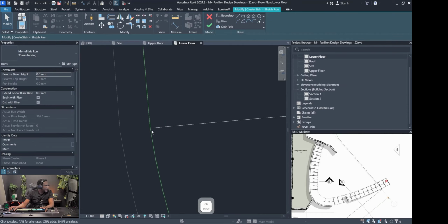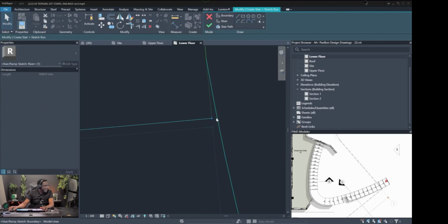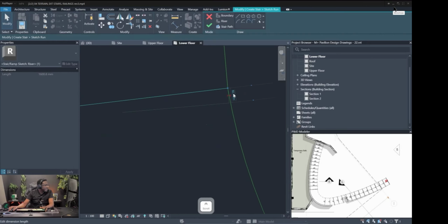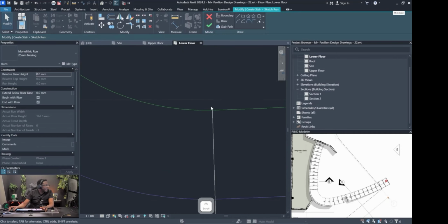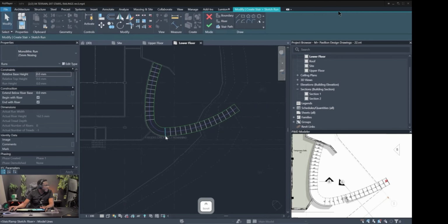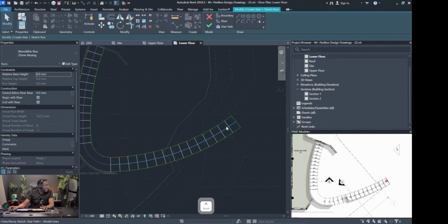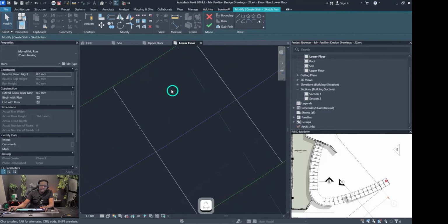And if we look, there is our problem. We can't have a riser that's not touching the stairs. So we need to actually move this and touch it right at this point. Yeah, so that was, we hope, what was causing it. Let's check the others. That seems to be okay. All right, let's try again. Okay, we still have areas that need fixing, so let's continue to check.